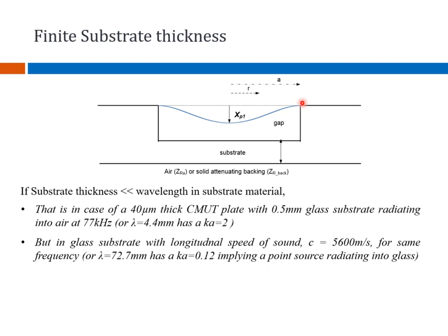Because these vibrations are being counterbalanced, you will have maybe out of phase vibrations at the backing, in reaction to the vibrating plate that you have bonded to the substrate, because the substrate is counterbalancing those vibrations. But since the impedance is different, the wavelengths in these two media are different.